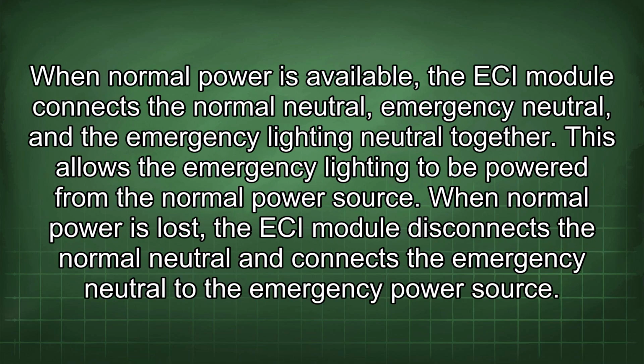When normal power is available, the ECI module connects the normal neutral, emergency neutral, and the emergency lighting neutral together. This allows the emergency lighting to be powered from the normal power source.